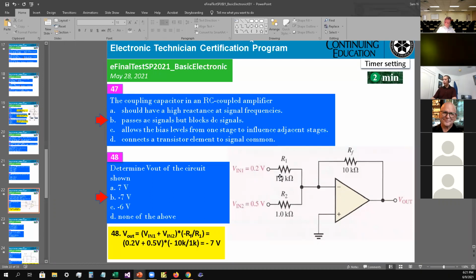Since you have the same input resistance and the same feedback resistance, the one in the handout used 3 resistors, but it went like minus, then the quantity V1 plus V2 plus V3 times the gain. If you remember that, you just add the inputs and then multiply by the gain. That only works if the input resistors are the same for each input channel. Yes, you got it.